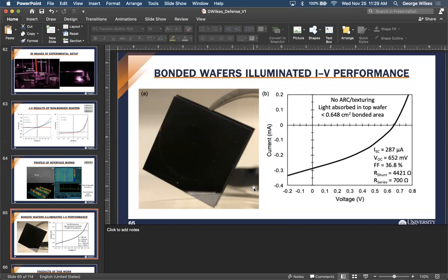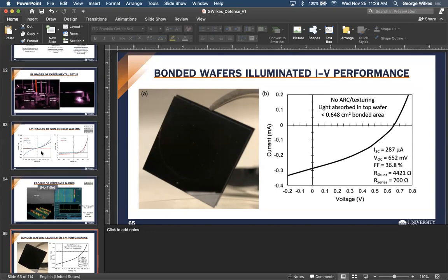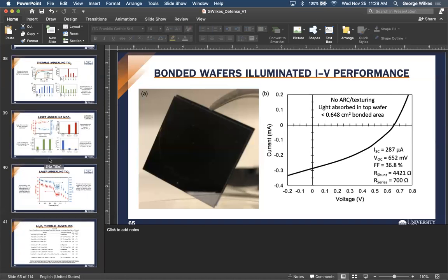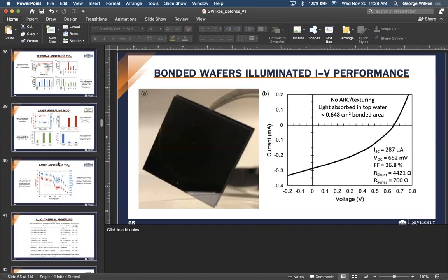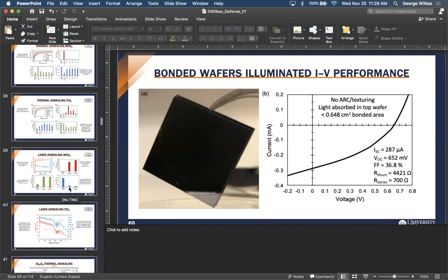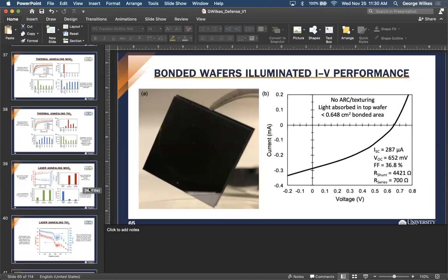And then a few other questions are about your laser annealing of the metal oxide. The general question is that you see a significant improvement when you do the laser annealing of those metal oxide materials, so I'm wondering what the major effect is from a material point of view. Does it just improve the crystallinity or increase the grain size, or do you think there is any effect on the oxygen vacancy and the stoichiometry? What is the major impact on those oxide materials when annealed by laser versus just furnace annealing? What would be the major difference, do you think?